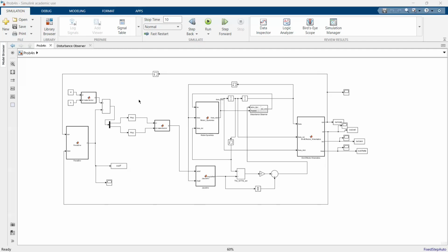And lastly, what happened in the Y: because it never touched the ceiling, the actual force stayed at 0 Newton instead of the target 5 Newton. Finally, physical realism matters. You cannot command a robot to build tensile force on a passive environment that can only push back with compressive force. Thank you all for listening, and that's all.